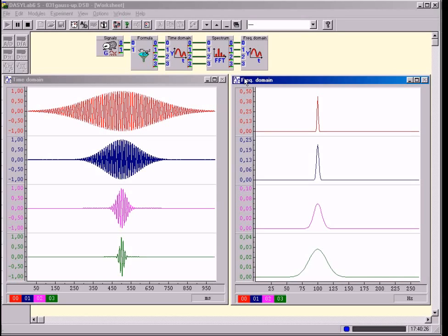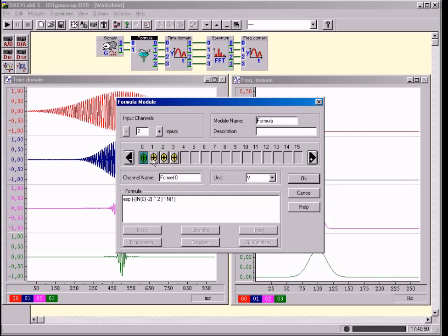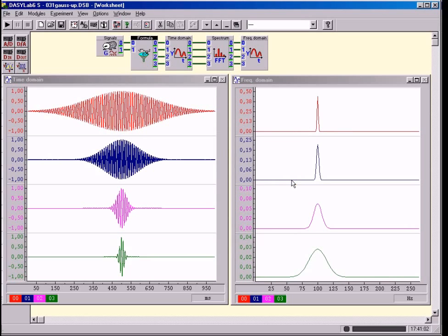At first, we must agree on what is meant by bandwidth and time duration. Here, a so-called Gaussian oscillation pulse is gradually restricted in time, set up by the formula generator. The Gauss function envelops a sinusoidal signal restricted in time, guaranteeing that the oscillation pulse begins gently and ends gently without any abrupt changes. As a result of this option selected, the spectrum occurs also as a Gauss function. It also begins and ends gently.